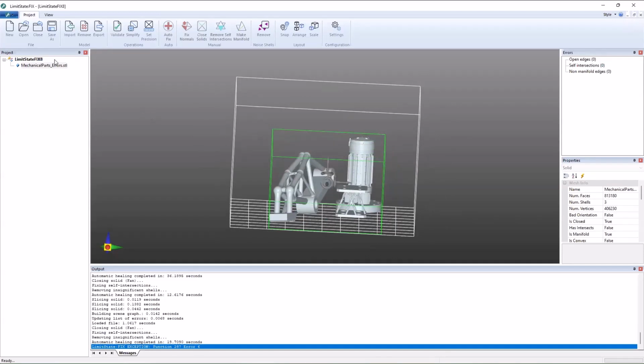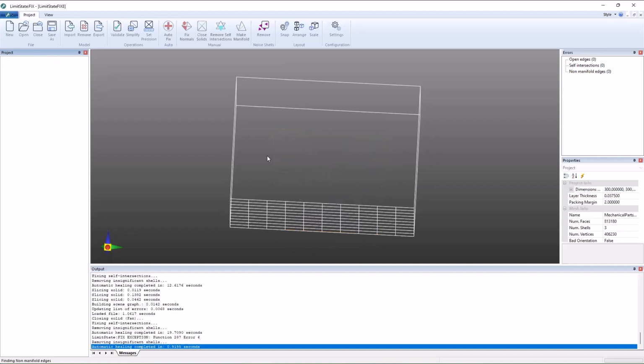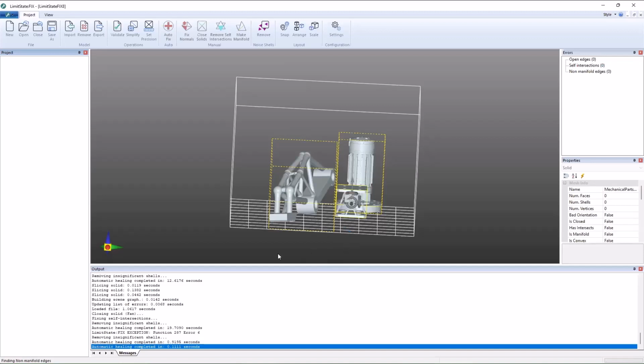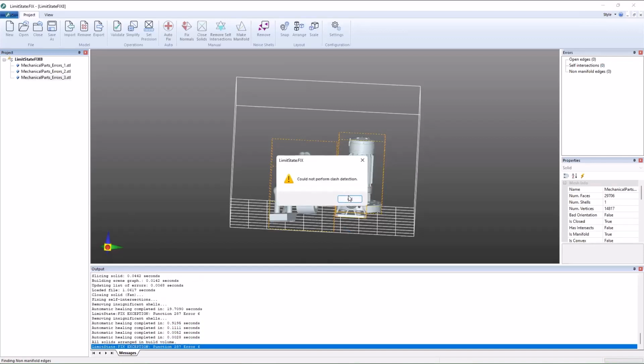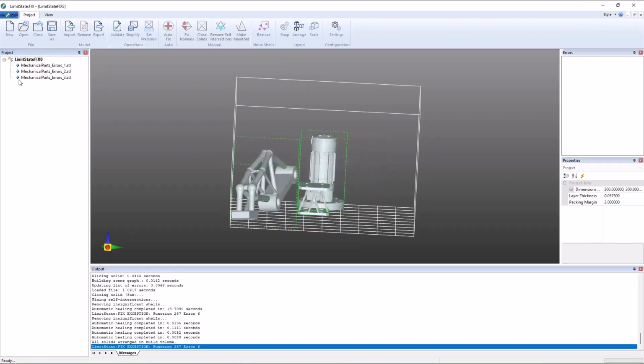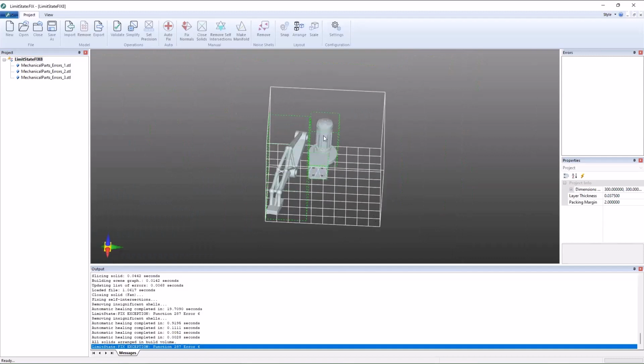And the same, we're going to look at converting it to parts. If I right click here in the project and click the convert to parts option, what you'll see happen on the screen is it will take that one object away, and replace it with 3 individual parts. We can see that they're all fixed, and they've also been oriented to the back left of our platform there.